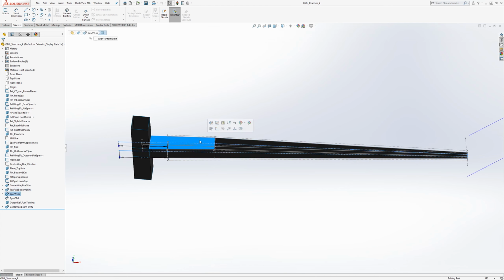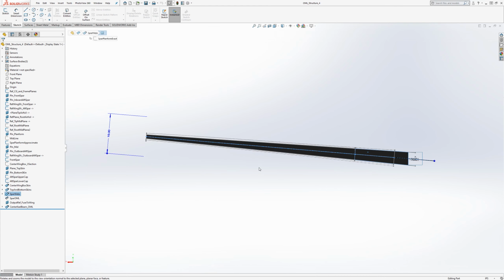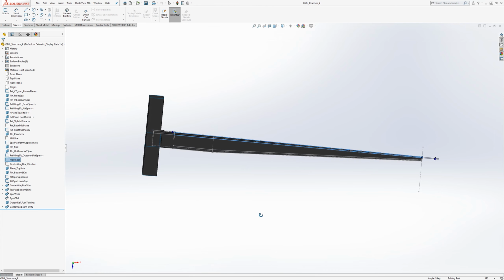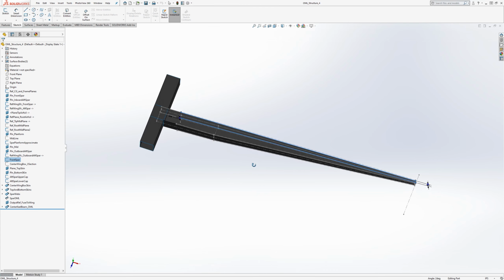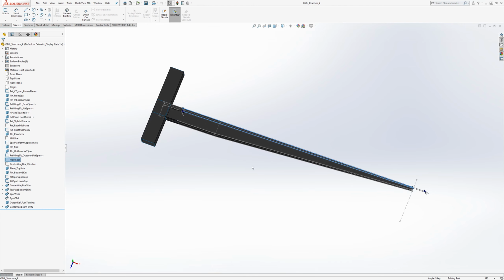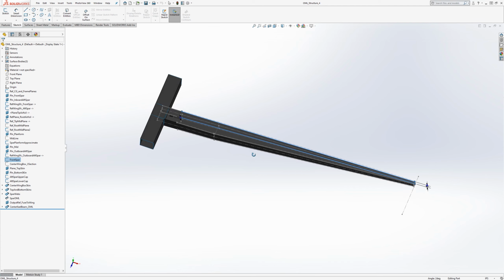But then if we go normal to this, it's straight the entire way. So that's what I was going for, just to break up the changes in angle of the spars into different areas of the structure, so that different fittings can just have one change in angle to deal with and not changes in angles in 2 different planes.